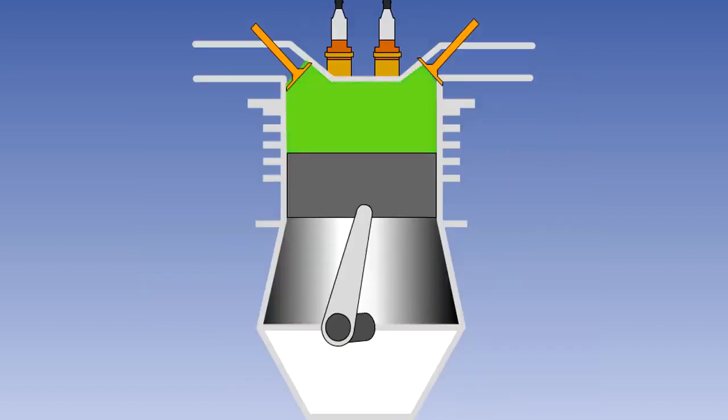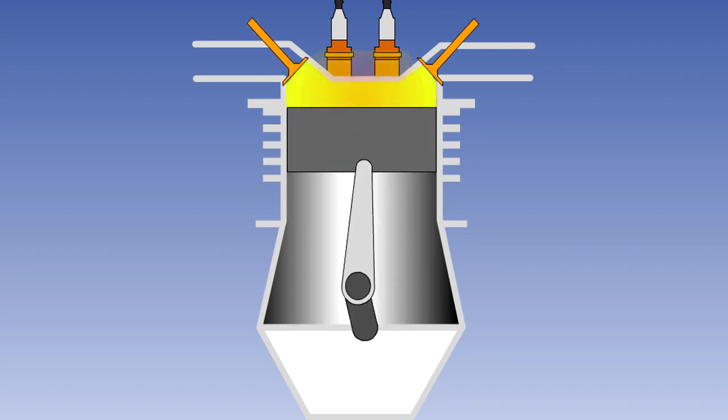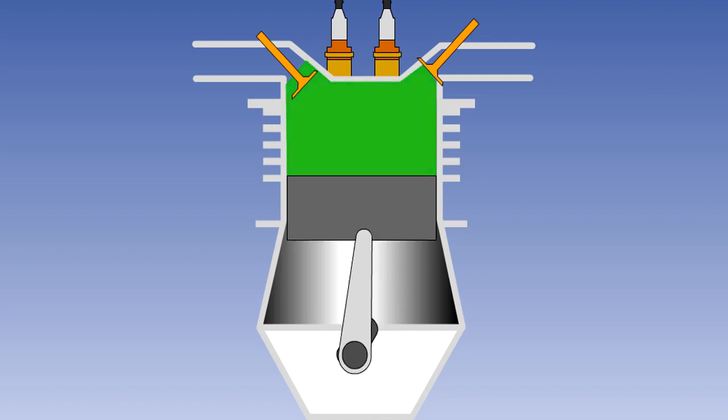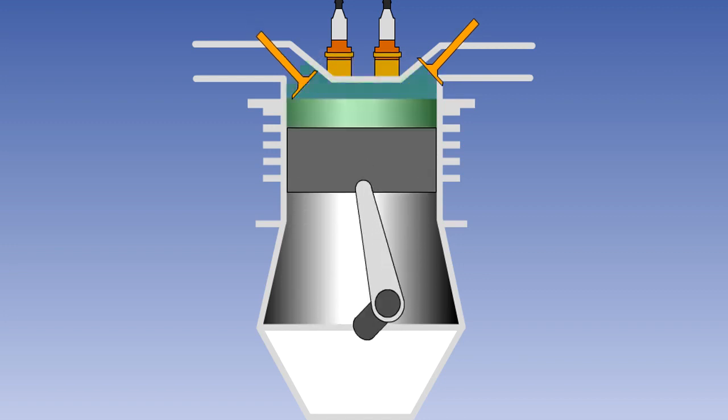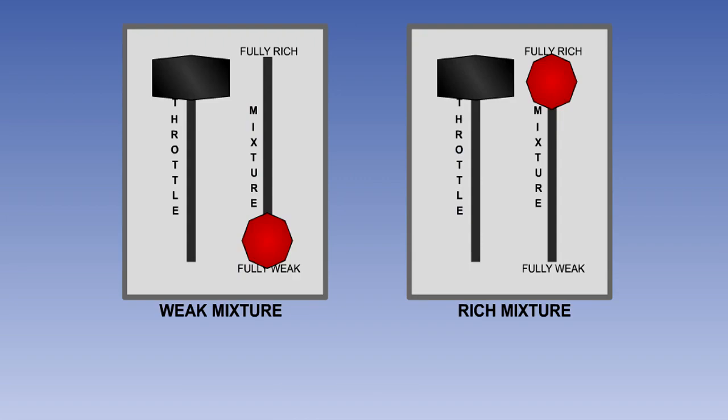Aviation gasoline is graded by octane rating. The octane rating of a fuel is a measure of the fuel's resistance to detonation when subjected to high temperature and pressure. A fuel's octane rating is checked in a test engine with the fuel-air mixture weak and with it rich. This gives the fuel 2 octane ratings. The weak figure is used in the fuel's name.